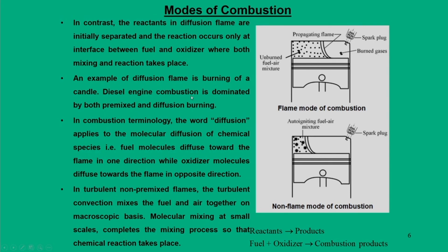Diesel engine combustion is mainly dominated by premixed as well as diffusion burning. So, we cannot exactly say it is a diffusion flame, it is a combination of both. However, SI engine combustion is purely dominated by premixed flame. But by definition, if you go back to combustion terminology, the way we defined the premixed flame, mixing takes place at molecular level and the mixture is homogeneous.